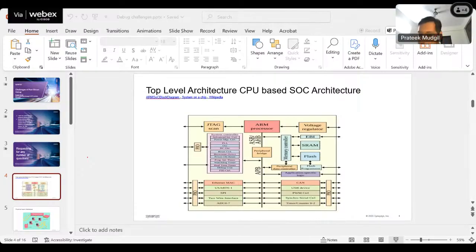One example I can take: you might have read in the transmission lines chapter in BTech about impedance calibration, where if impedance mismatches, there are reflections. This is related to waveguides, a concept we read in BTech. Let us say this is a port whose impedance is 100 ohm, and we connect to a board or another IC with 80 ohm impedance. When data is sent, because the impedance is not matched, data is reflected back to the same port and does not go inside.